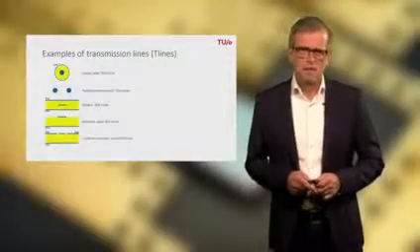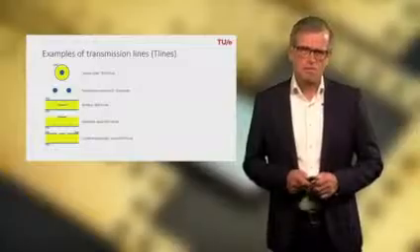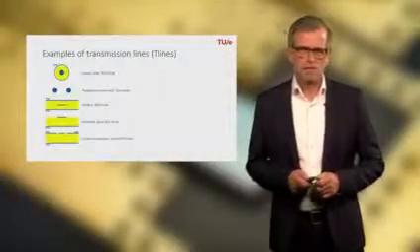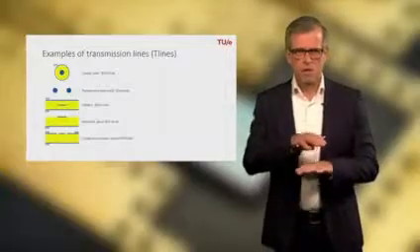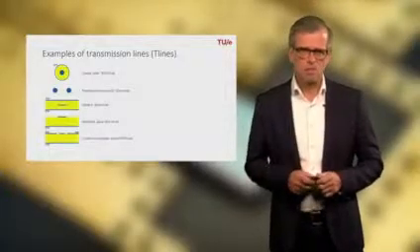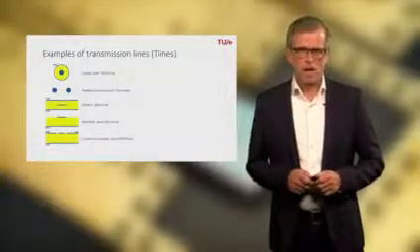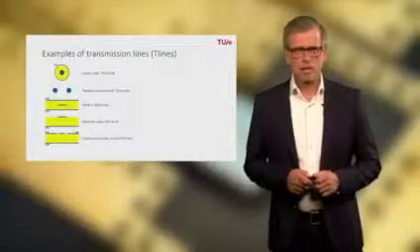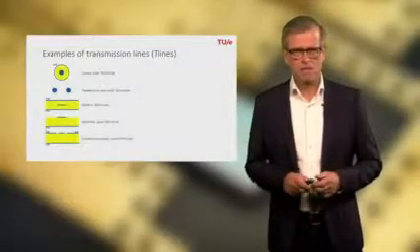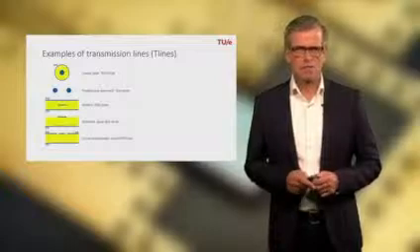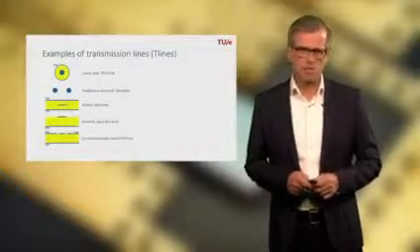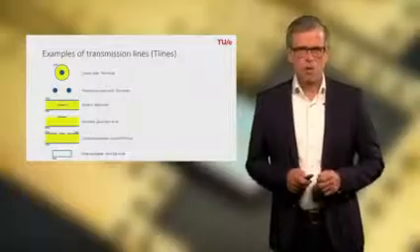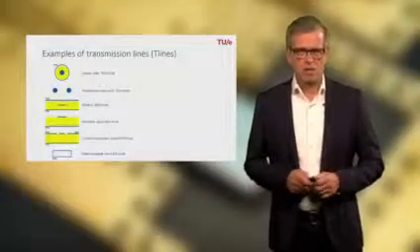More modern versions of transmission lines are all embedded in planar technologies like PCB technology or semiconductor technology. Examples include microstrip lines, strip lines which have 2 ground planes and in between a strip, and coplanar waveguide transmission lines, which in principle do not require a ground plane at the bottom, and they are often used in semiconductor technologies. Another type of transmission line is a waveguide, either rectangular or circular.